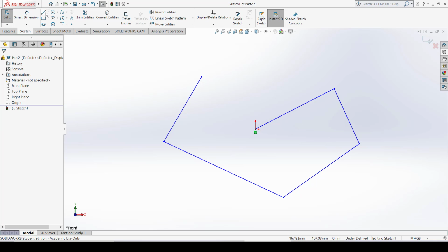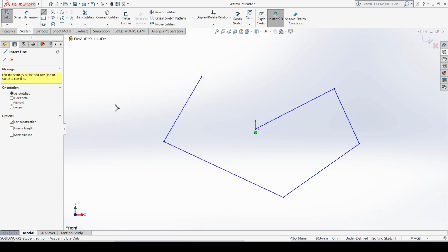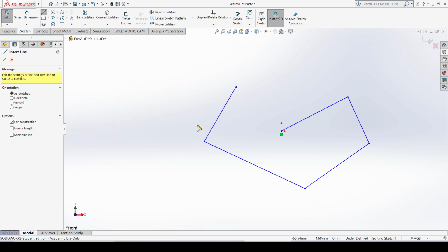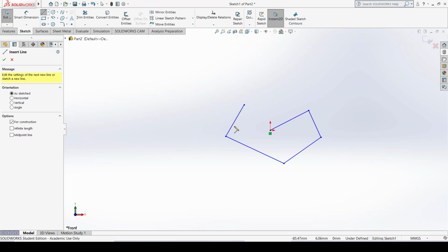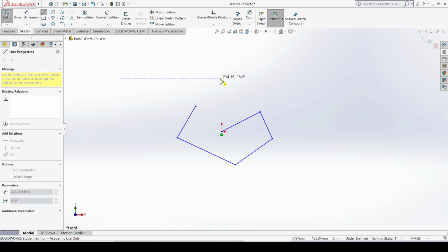Now, if you want to draw another type of line, that is called the center line. The center line is basically used for reference purposes. It does not have any characteristic value when you use it in the 3D module also. It is used for center lining, providing centers of circles, providing the center of an object or your drawing, or for reference purposes. So I just click center line here. This is different from the basic standard line. When I click on it, I can draw anywhere on the screen. Okay, so see, this is your center line.